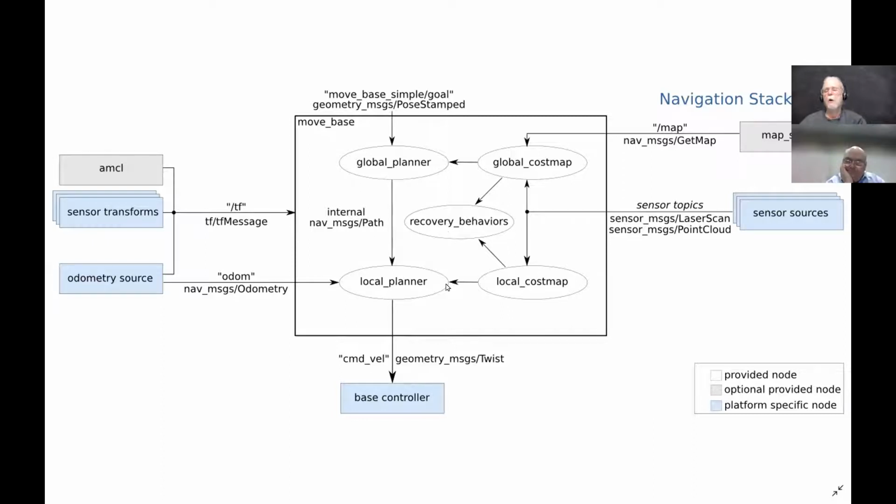And then somebody's going to say, well, what about TEB Planner? Well, it turns out TEB Planner loads a different local planner. TEB Planner gets loaded in here as your local planner. It replaces the local planner that's there. And then you have the option, if you don't make any changes to it, it puts out a standard command velocity message, which could go through the translator and run my Ackermann stuff directly. Or in the TEB Planner, you can set a checkbox, say, no, we want to use the modified version that puts out a steering angle into the modified command velocity. So that's just a couple of notes there on what's inside of what I'm calling the